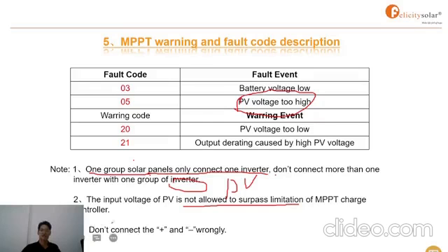And number 3, don't connect positive and negative wrongly, because in some countries the positive and negative power cables are the same color. Maybe all of them are red, or black, or blue or something like that. You need to pay attention to that.